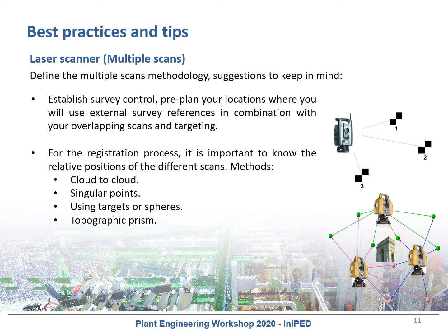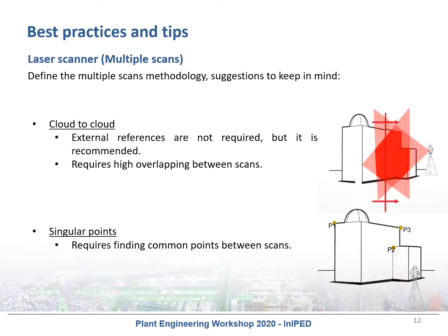This process is called the registration process, where you use different methods: cloud to cloud, singular points, targets or spheres, and the topographic prism. The cloud to cloud method requires a high overlapping between scans, and we recommend to use external references. The singular point method only requires finding common points between scans.